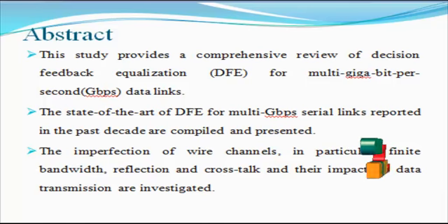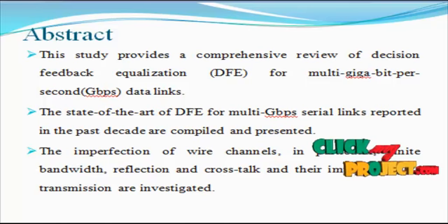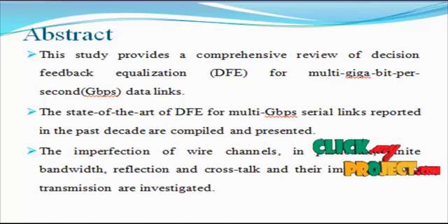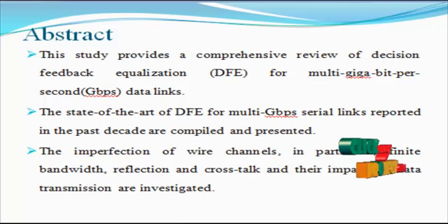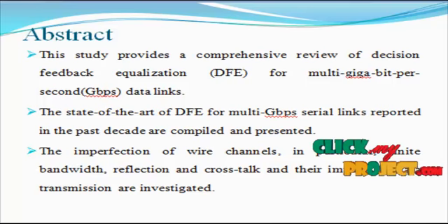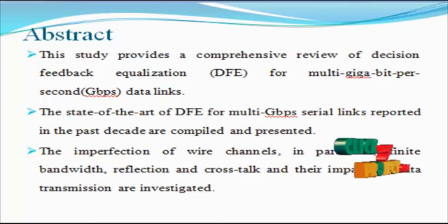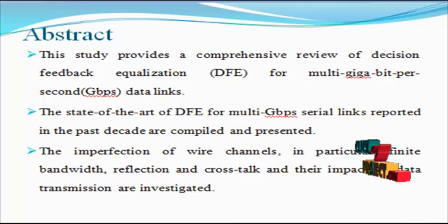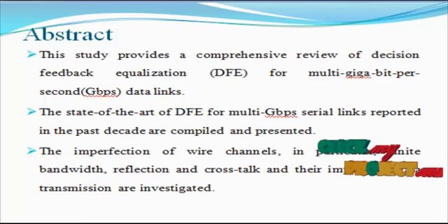A detailed examination of the principal configuration, operation and limitations of decision feedback equalization follows. Design challenges encountered in the design of decision feedback equalization for a multi-gigabit data link, including timing constraints, sampling, error propagation, arithmetic operation, highly dispersive channels and power consumption, and techniques and circuit implementations that address these challenges are studied.